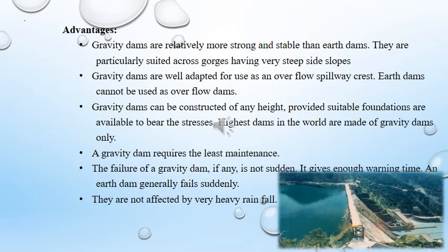So, the advantages of gravity dams: gravity dams are relatively stronger and more stable than the other, that is, the earthen dams. They are particularly suited across a gorge having very steep side slopes, and gravity dams are well adapted for use as an overflow spillway crest.